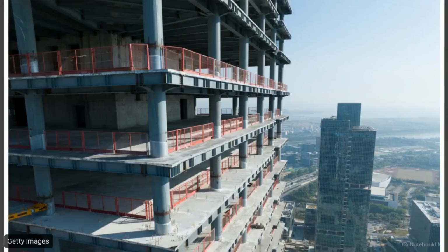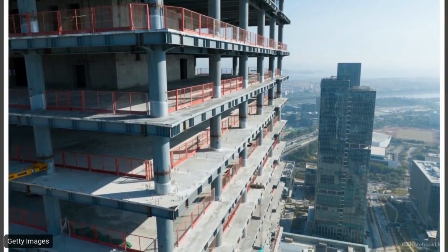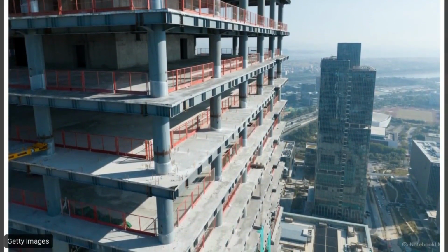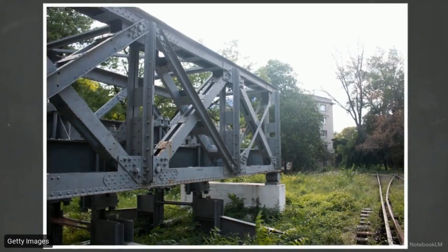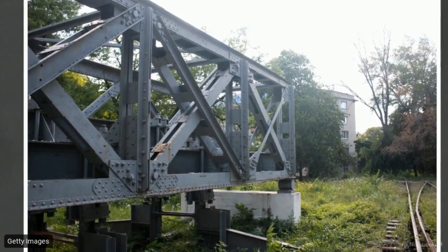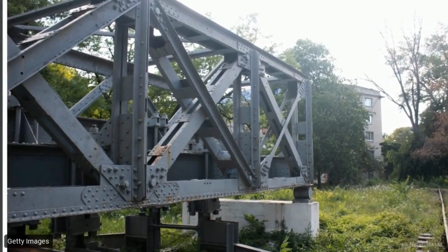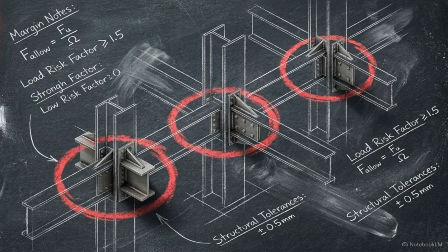For material resistance governed by standard yielding, we use a baseline gamma M0 factor of 1.10. Compare that to connection resistance, like bolts or shop welds. These require a higher factor of 1.25 to account for potential fabrication errors. By splitting these safety margins into partial factors, engineers can assign specific mathematical risk values to precise uncertainties.